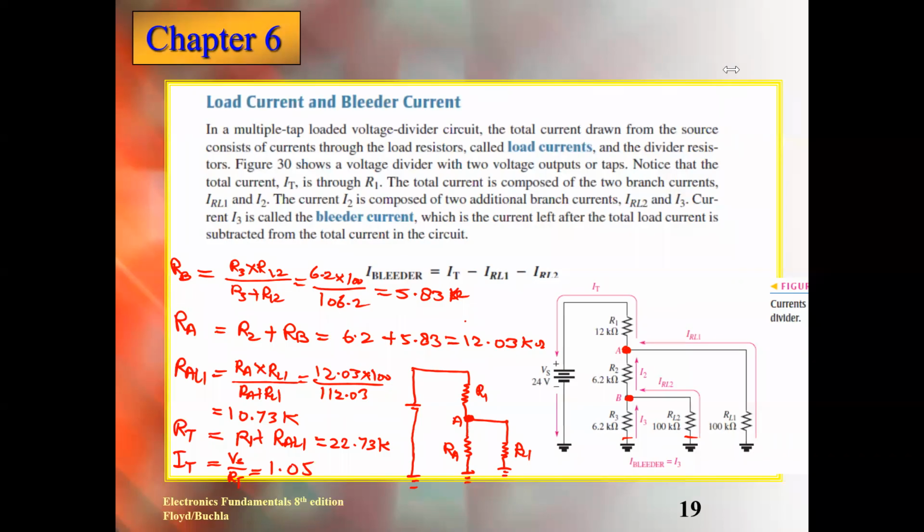Milliampere. I told you, you should check the value of the resistance, which is in the denominator. And now it is in kilo. When it goes to the numerator, it will be in milli. So be careful about it, otherwise you will lose the marks. This is kilo, 10 power 3. When it goes up, it will be milli. This is milliampere, IT. Now you know the total current. So total current and the I1, will it be the same or different?